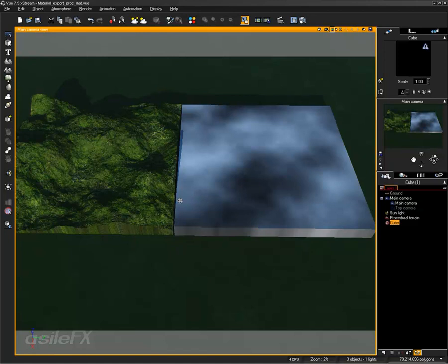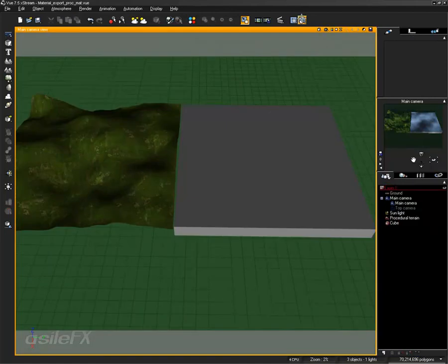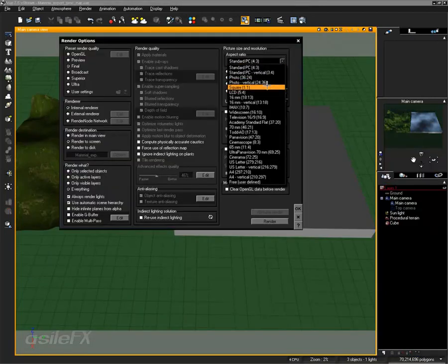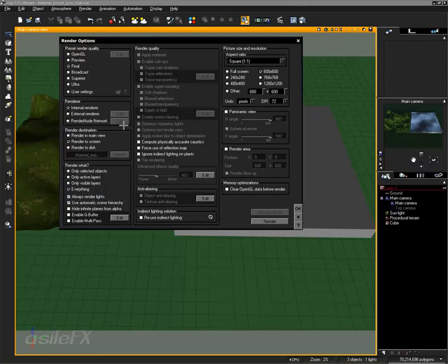the terrain. And what we can do is now set the camera to render this object, keeping it within the bounds. So what we need to do is change to a square render mode. And now this resolution you can set to whatever you want. The ratio will need to be the ratio of the terrain. Since we have a square terrain, we could just use square. But if you did modify the scale, you will need to find out what the change is, set up an aspect ratio so you can lock it in place and render it correctly.